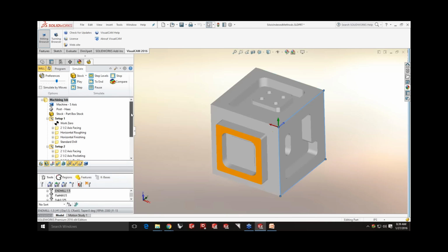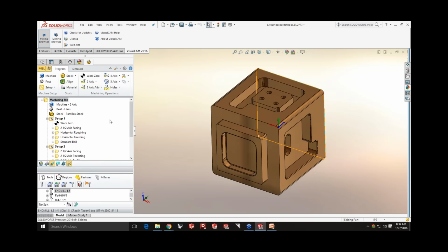Now, if you have a 5-axis machine tool, you can post-process the entire operations to one output file. Now, if you're working with a 3-axis machine tool, you can still create additional setups, but you would have to refixture or reorient the part and then post each setup out separately. So the Pro configuration offers the feature to be able to create multiple coordinate system setups, so you can basically reorient your coordinate system to any given orientation to program the part.